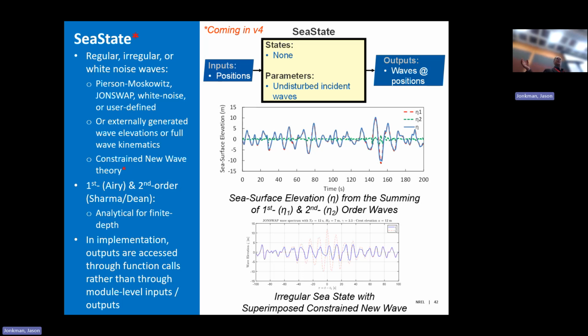It uses the same characteristic irregular SeaState, but it basically embeds this extreme wave built up, and it follows sort of the physical process where normally what happens is you get some waves that sort of get phase aligned and boom, boom, boom, it builds up, and so you see it. And so basically this constrained wave allows you to make sure that big wave shows up at the time you want, at the location you want in the wind farm. So that's quite a powerful feature.